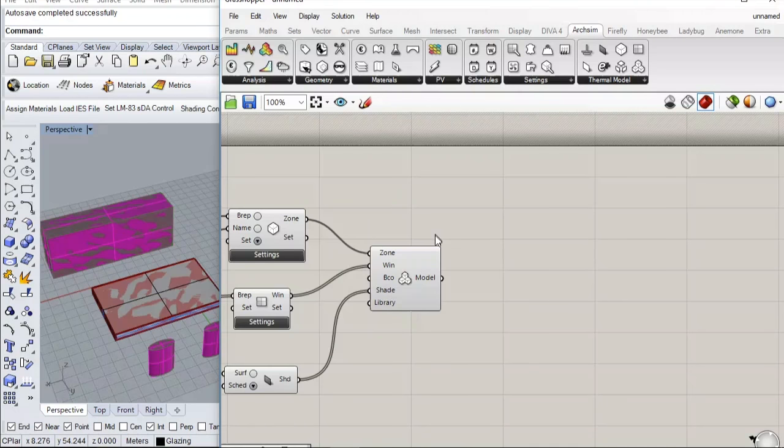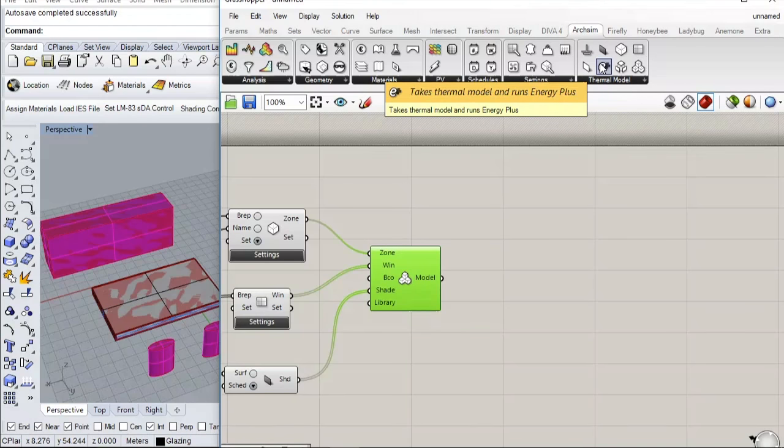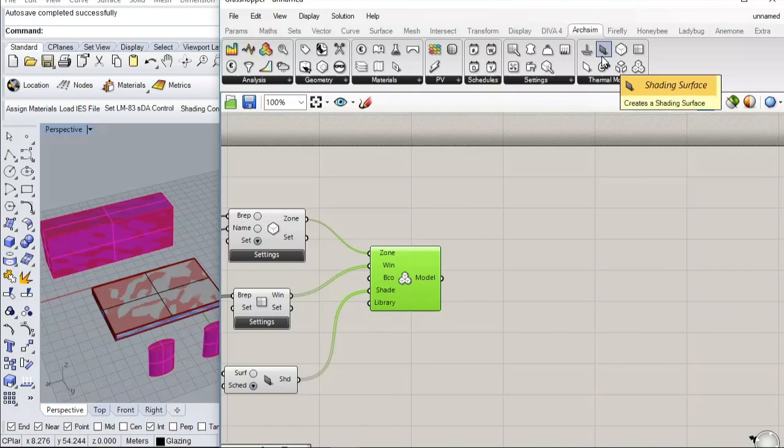This model now represents an ARCHSIM geometry model, and these settings, which we'll get to in a few minutes, will speak about the conditions of building fabric, occupancy, the quality of glazing, etc. But for the energy simulation calculation, we need to bring in the actual calculator that does the number crunching and predicts the energy consumption for us, which is Energy Plus, this physics-based energy simulation model that does a kind of deep hourly or every 15 minutes, in this case, simulation of energy consumption based on geometry and site climate.